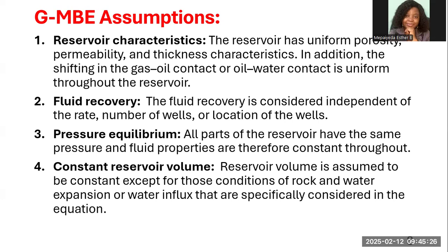And secondly, the fluid recovery is considered independent of the rates, the number of wells, or the location of the wells. This is also one of the assumptions in the material balance equation, that no matter where the well is positioned, the number of wells, or the rates of production, reservoir fluid recovery can still be ongoing. And then thirdly, pressure equilibrium.